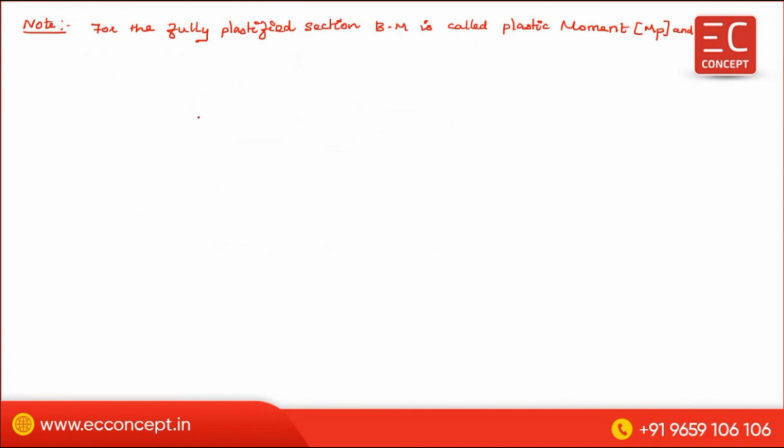For a fully plastified section, the bending moment is called plastic moment, that is MP, and the curvature becomes infinity.